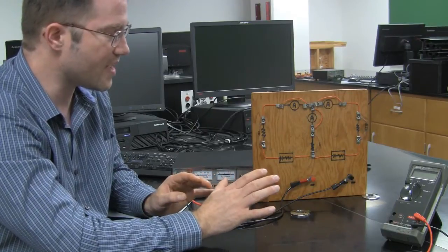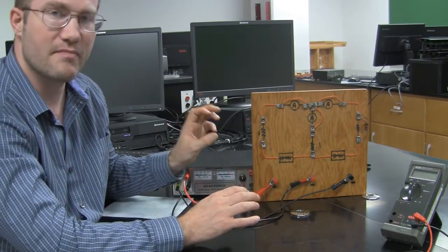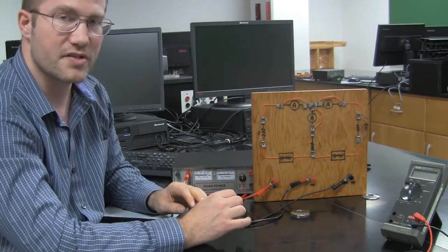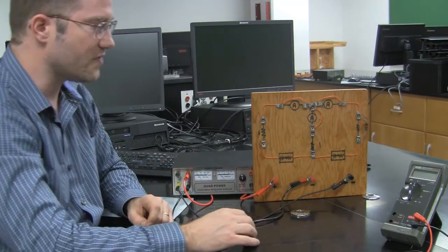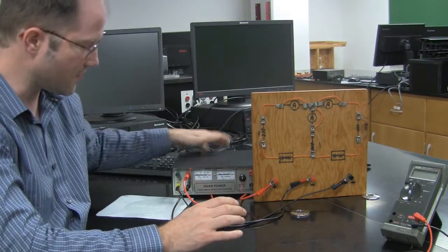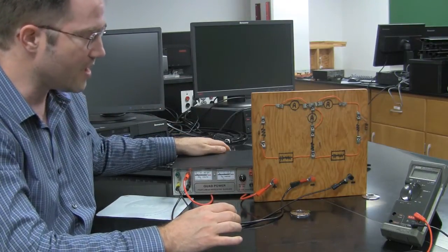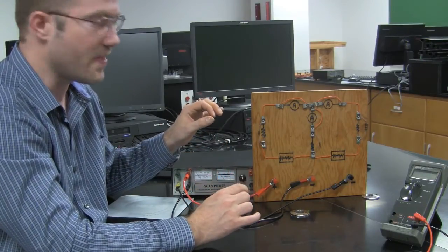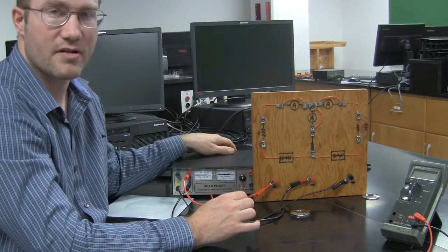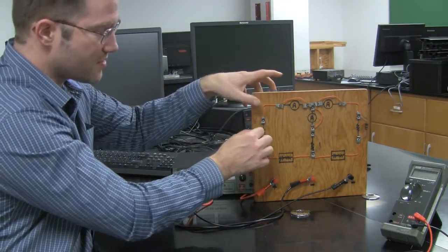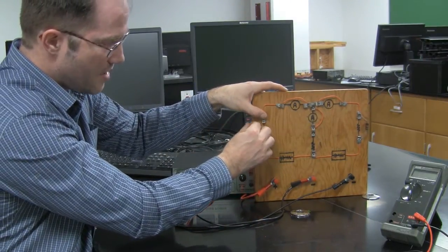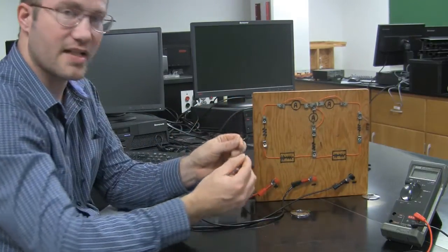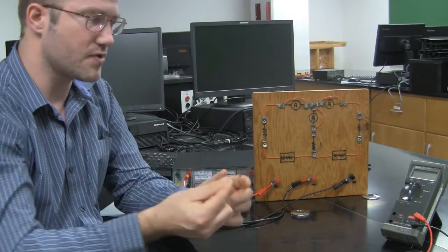Now when we perform this lab, we're going to actually measure the values of these resistors and the values of those three voltages. First of all, before I turn on this power supply, I want to measure my resistances. When you measure resistance that's in a circuit, you have to turn off the power and you have to disconnect the resistor. I can do that by pushing down on this tab and pulling the resistor out. I can take the resistor completely out, and now I have this resistive component here.